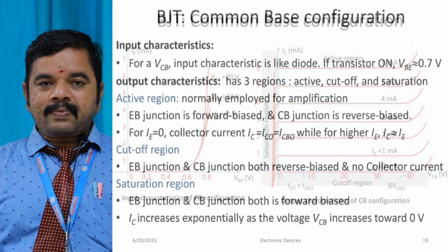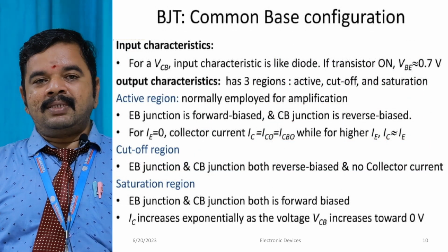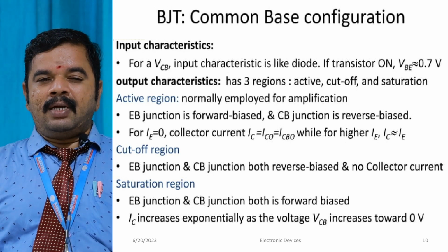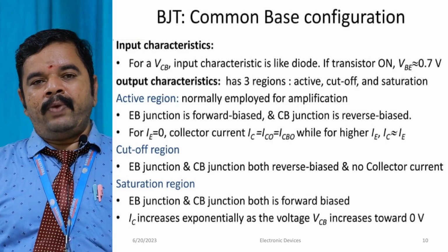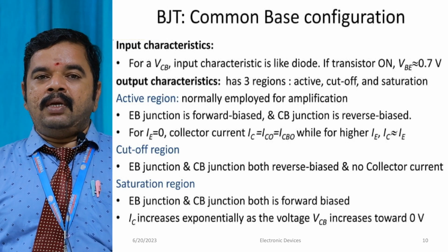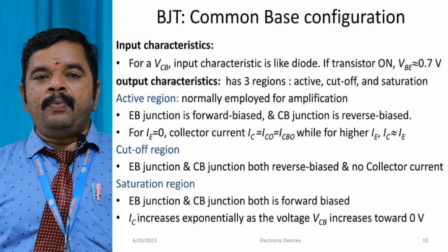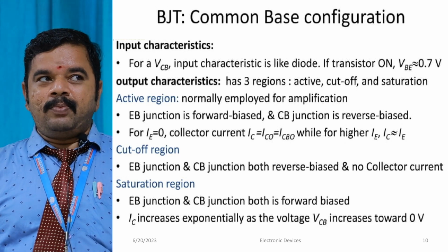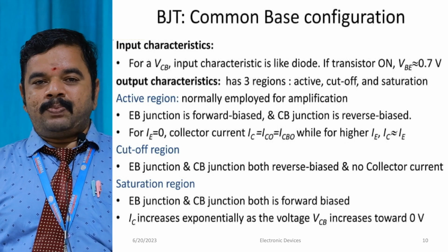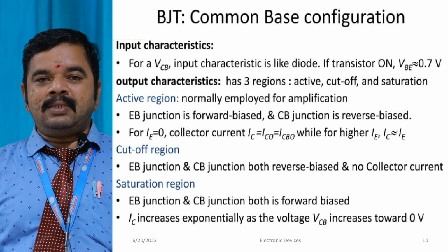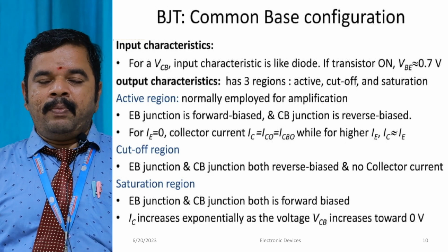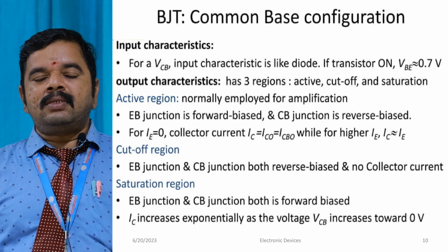Then next, what we are going to discuss is the input characteristics and the output characteristics. What are input characteristics? Why do we have to go for these characteristics? We have to define how the particular configuration works. In the common base configuration, input characteristics means we have to plot the graph between the input voltage and the input current for a constant output voltage.